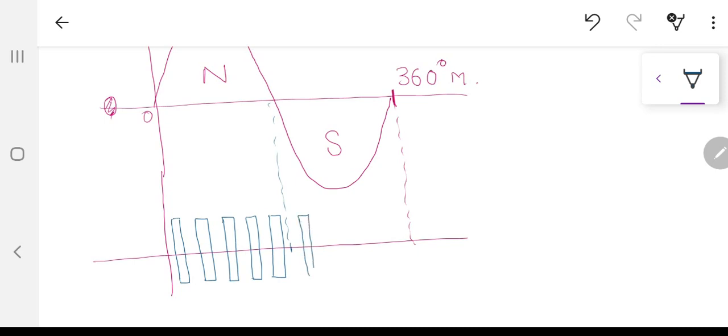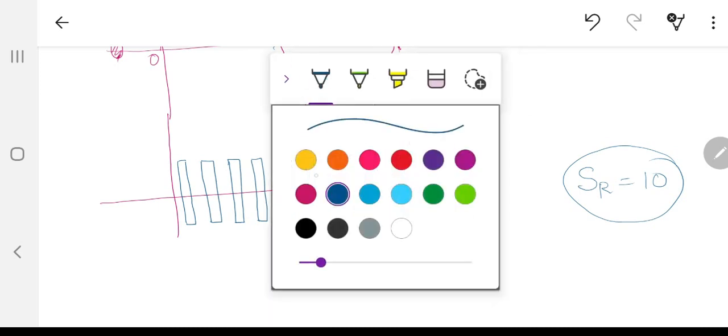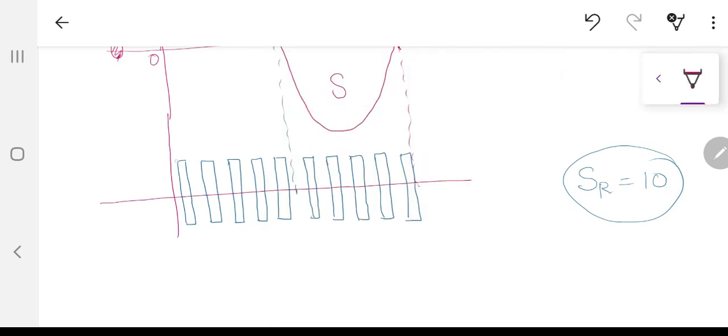And if I have 5 more inside under the south pole, these are just rotor bars. This is very important. Now these are 10 rotor bars, which means that my number of rotor slots is equal to 10. Now based on these rotor bars, there is going to be an end ring, and that end ring is going to short all these conductors like this. I hope you are getting the idea.